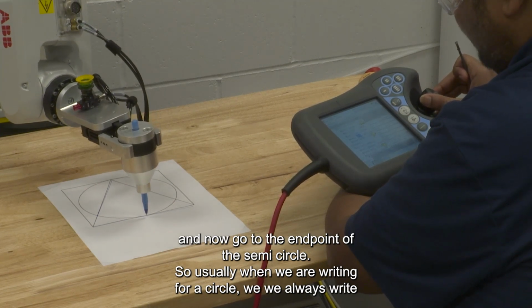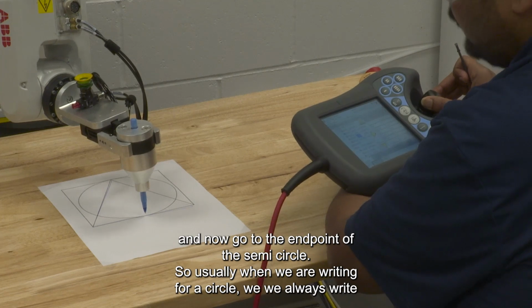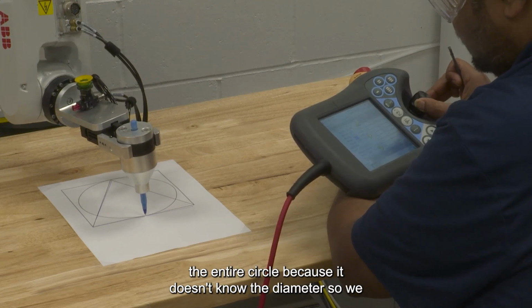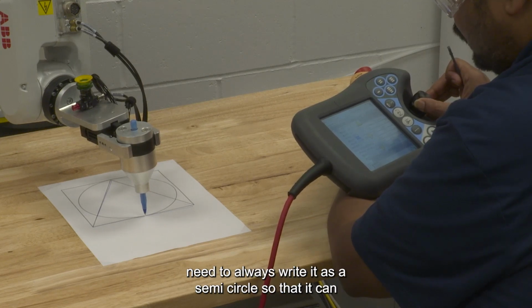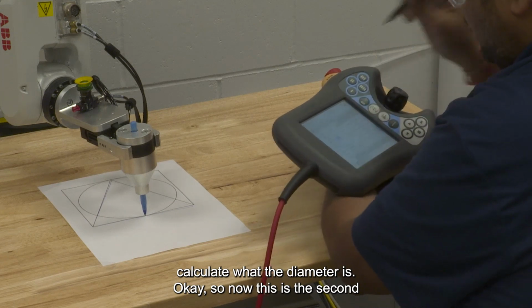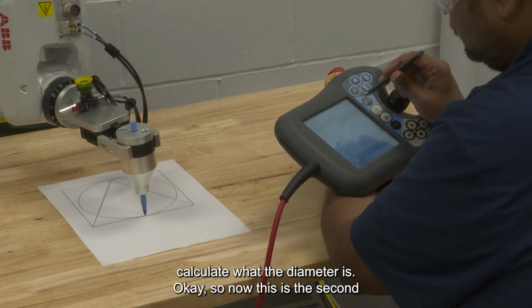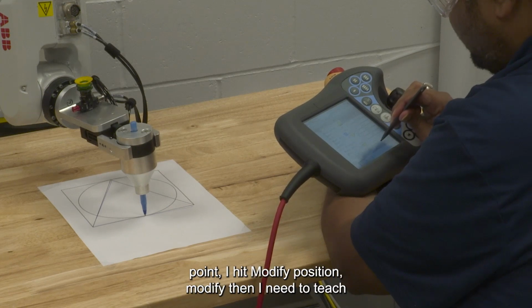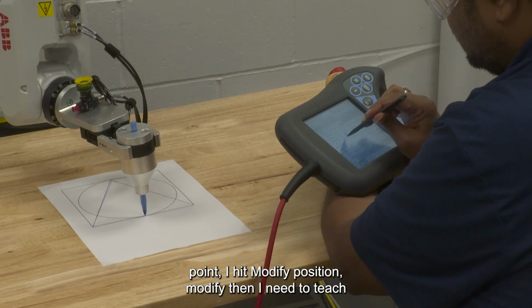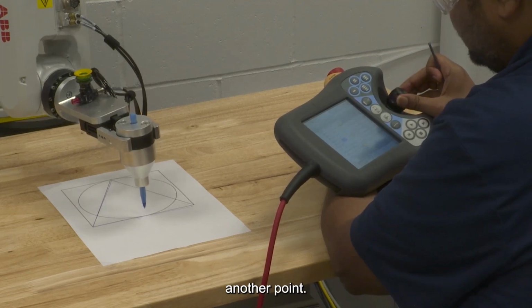Usually when we are writing for a circle, we always write it as 2 semicircles, not one single move C command for the entire circle, because it does not know the diameter. So we need to always write it as a semicircle, so that it can calculate what the diameter is. Okay. So now this is the second point. I hit modify position, modify, then I need to teach another point.